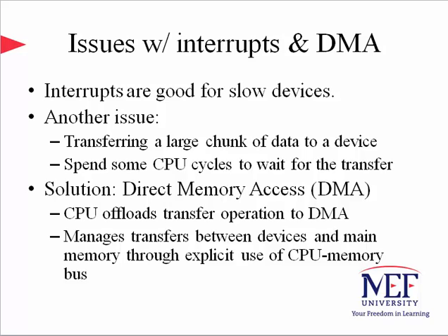If the speed of the device is not known, or sometimes fast and sometimes slow, it may be best to use a hybrid approach that polls for a little while, and then, if the device is not yet finished, uses interrupts. This two-phased approach may achieve the best of both worlds.